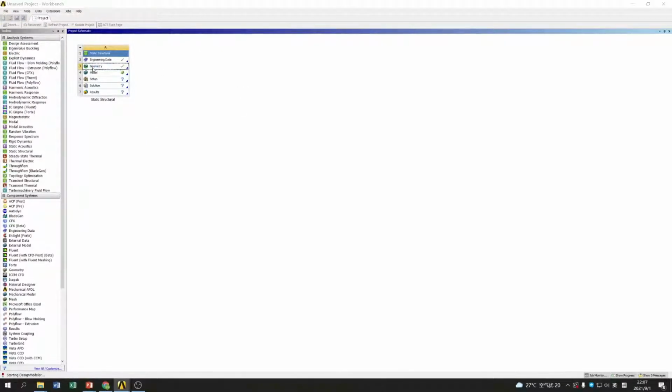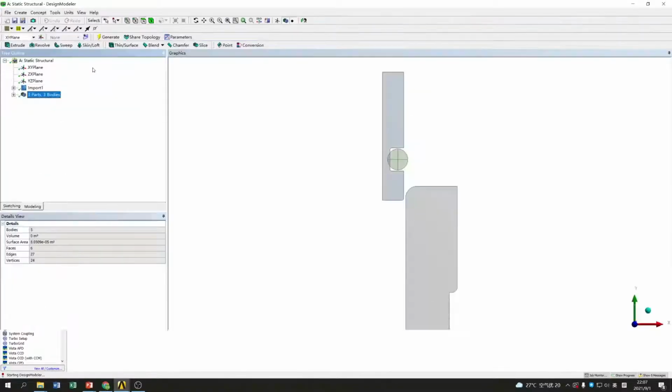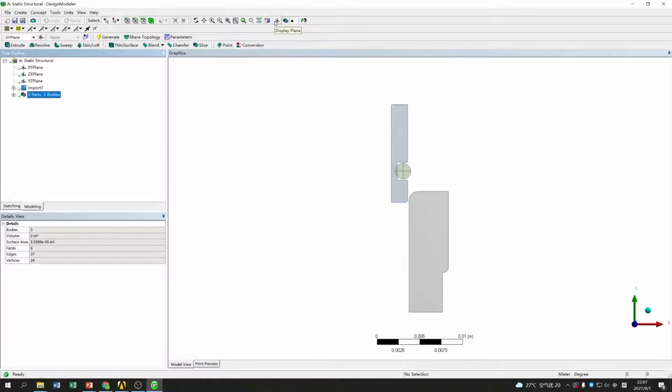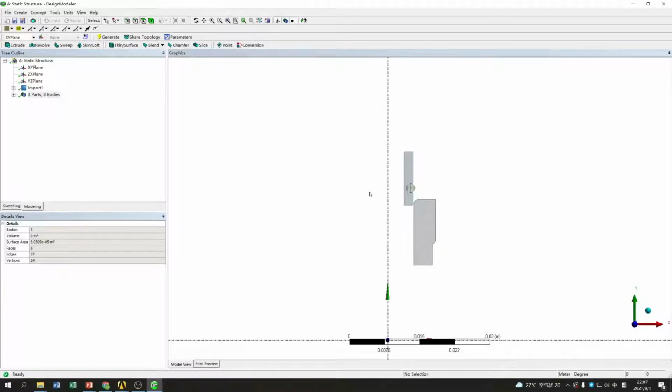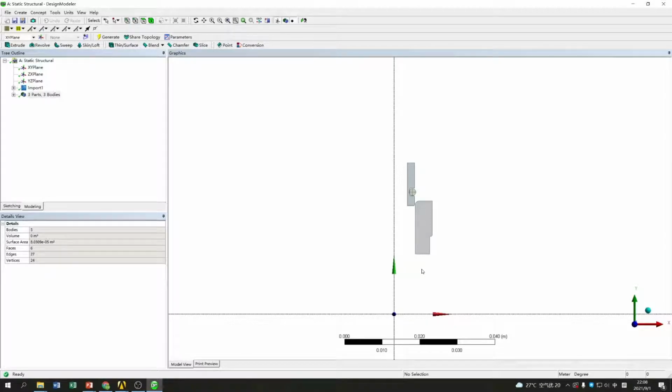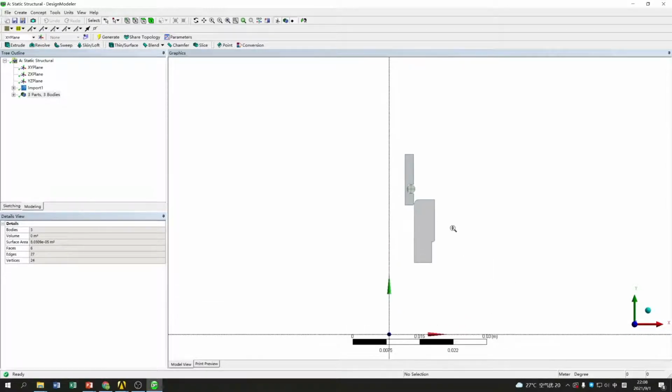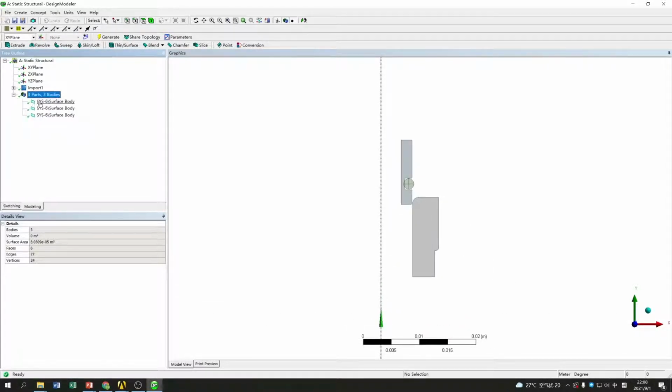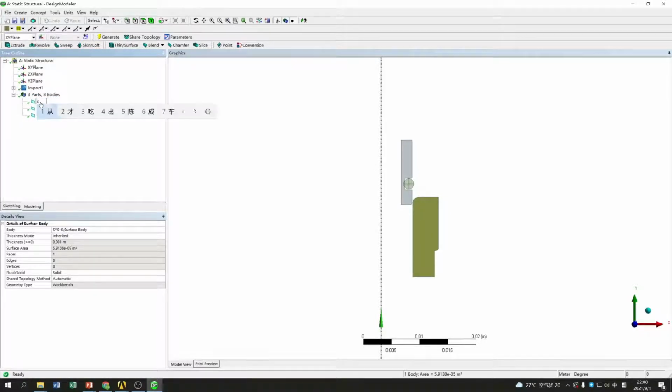I'm not going to show you how to sketch it because it is based on your design. But it's worth noting that the model is axisymmetric, and two-dimensional analysis will dramatically save computational time. So it is helpful to simplify the model into 3 surface parts on the XY plane. And we can rename it. This part to cylinder, and this part for piston, I think. And the circle one is the O-ring.